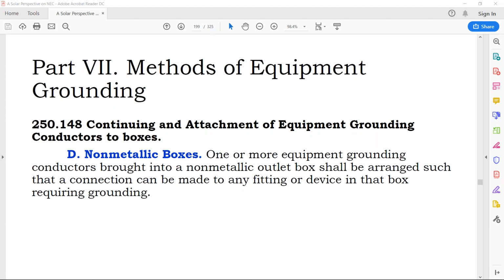Instead of having your metal fitting serve as an equipment ground path, where we connect our ground on one side of the box, connect the box to the ground, and take it out the other side with our conduit, now we have to use grounding bushings and connect the metal conduit on one side of the box to the metal conduit on the other side. And then you still may need a ground bar on that plastic box if you're doing splices inside of that box.